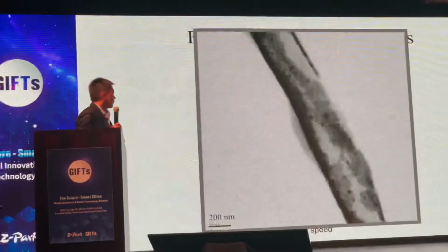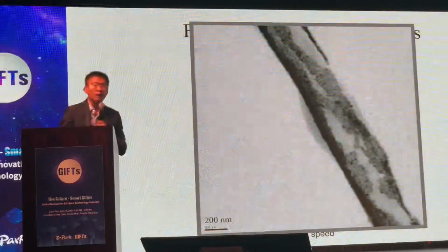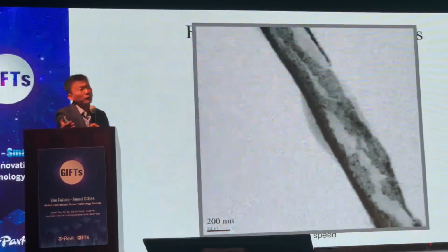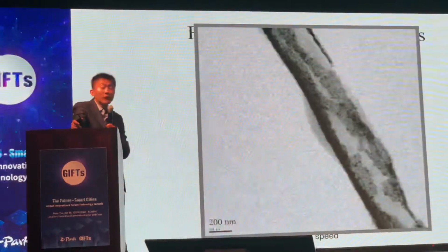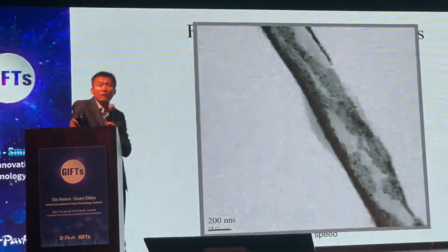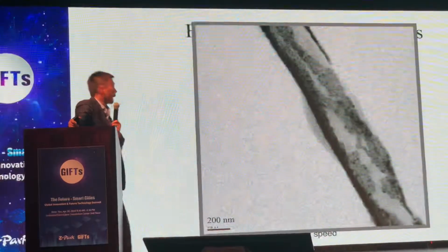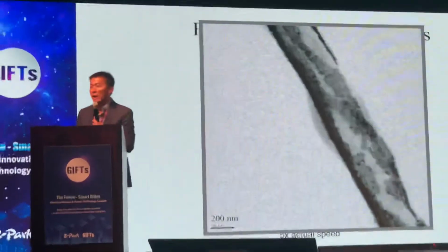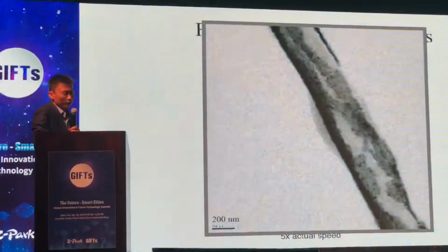This is an in situ transmission electron microscopy video, with very high resolution. You are seeing a 200 nanometer scale bar right there. Inside the electron microscope, we could see the silicon. Once lithium comes in, the volume expansion takes place, and it does not break in the nanowire case. But the coating, the black color is the copper coating on the surface, is really broken. This is really telling you how challenging it is to make silicon work.